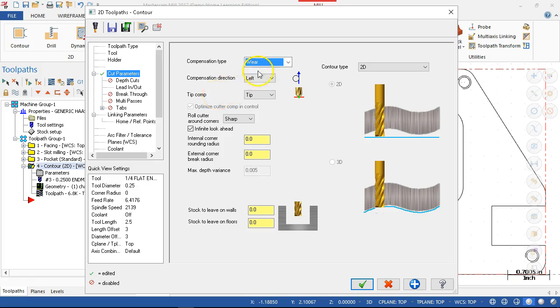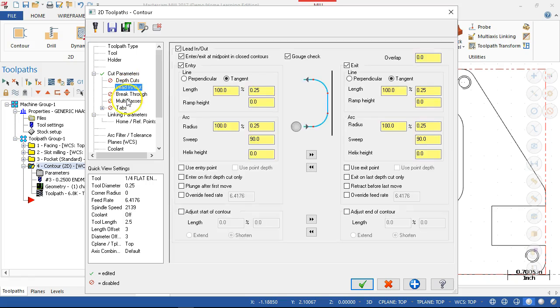And then let's see, depth cuts. We're still going to treat it as the full depth. Maybe we go with multi-passes, going to depth, stepping into the wall a couple times so that it gets into that corner and is not taking that full heavy engagement on the last pass. So lead-ins, we had our same numbers, and we'll be able to see a little bit closer.